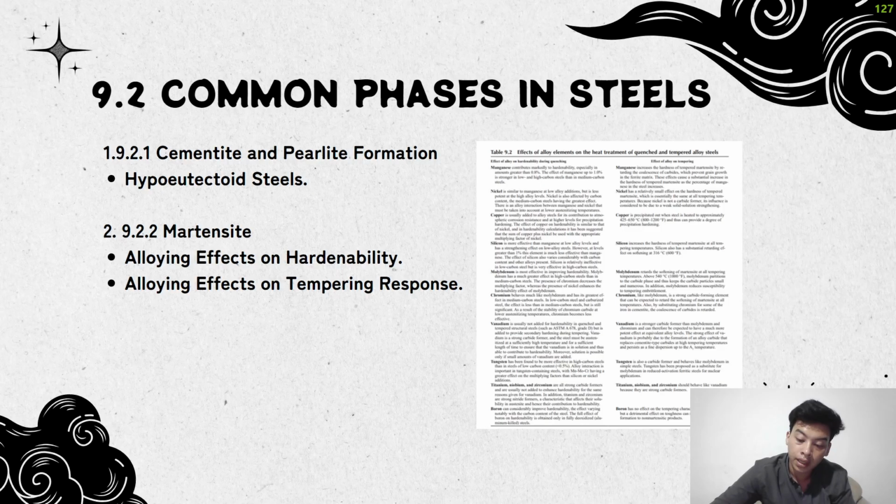Bainite. Bainite is a distinct metastable phase in steels that occurs when cooling rates are not rapid enough to produce martensite but are still fast enough so that carbon does not have enough time to diffuse to form pearlite. Like pearlite, the constituent phases of bainite are ferrite and cementite.